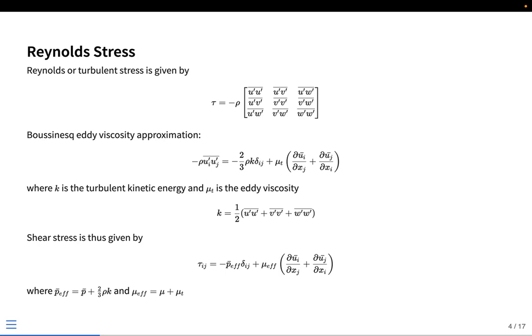And then we have something called the turbulent kinetic energy, which will give us the strength of how much these fluctuations are in a given fluid, followed by the definition of eddy viscosity, which is very similar to the form of the viscosity that we measure. The only difference here is that this eddy viscosity relates the viscous forces happening because of these fluctuations to an equivalent velocity gradient in terms of the mean velocity profile.